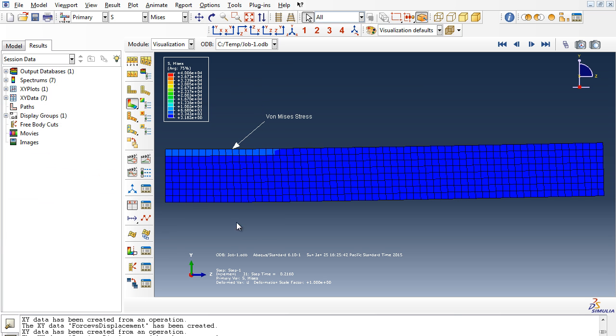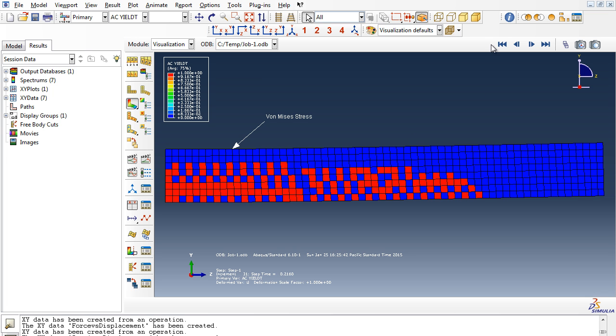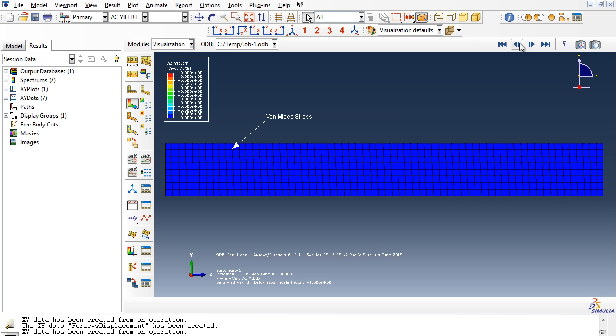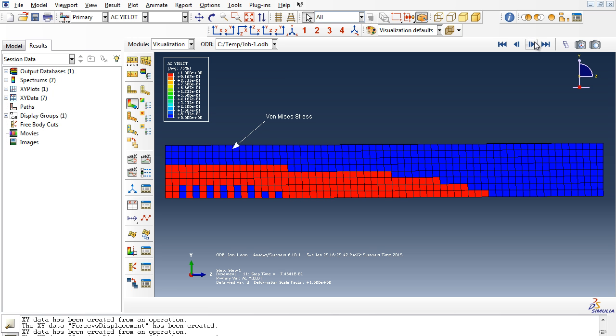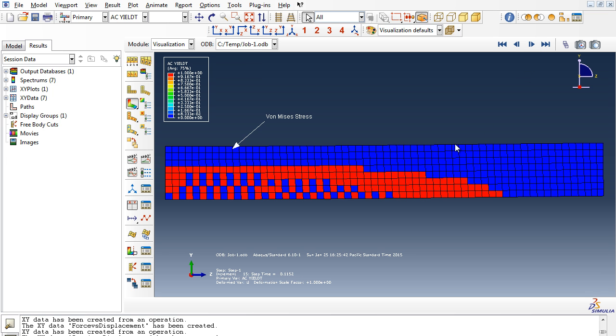So cancel that, dismiss. And now let's start looking at the crack patterns. These are the active yields, tension, and as the analysis progresses, you can see it increasing. And it's pretty raw because the mesh is 0.75 inches each cube. So if you decrease the mesh size to say half an inch, you're going to increase your analysis time by like 3 times. But it took like 10 minutes to run this analysis.